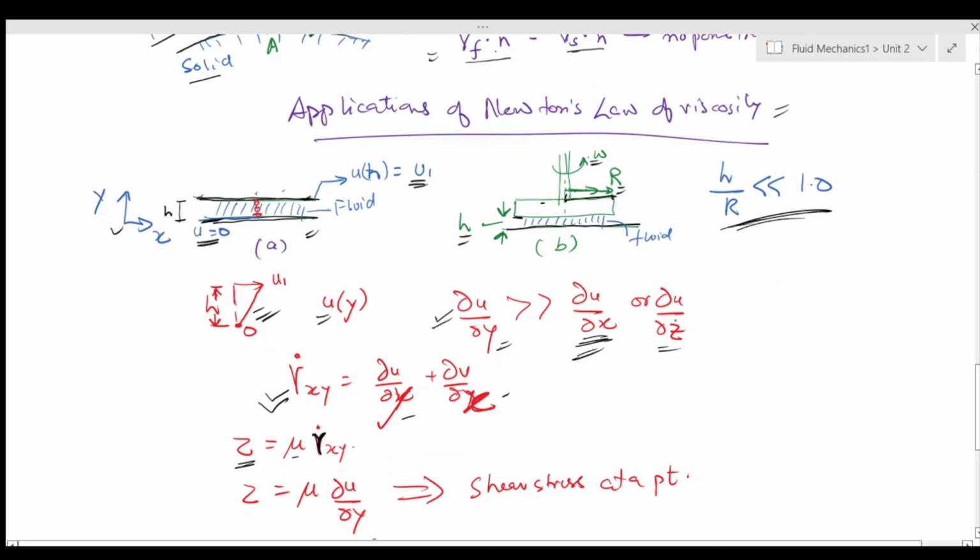That's what I'm saying here. The tangential velocity imparted to the fluid as a result of no slip condition has the largest gradient in the direction normal to the surface than in other two directions inside the narrow gap. Thus, the velocity variation only in the normal direction may be considered to be significant.